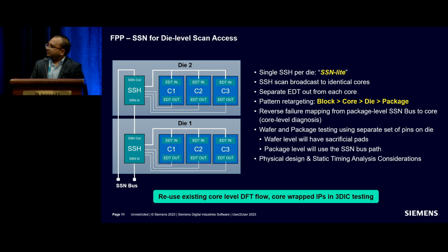And I think we term this thing SSN Lite. It's a term that we sort of invented, but SSN Lite gave us a way to still achieve what we want to do. This is probably not the most optimal use of SSN from a test volume perspective, but it still allows us to move forward with the intended testing for all of our current products.